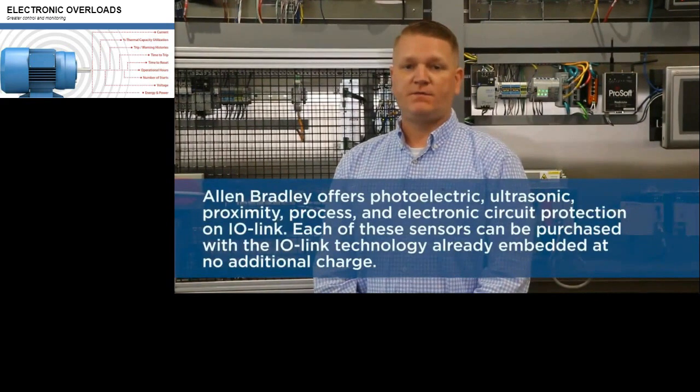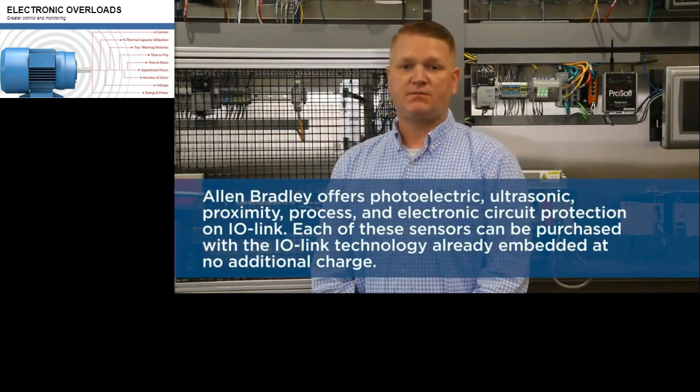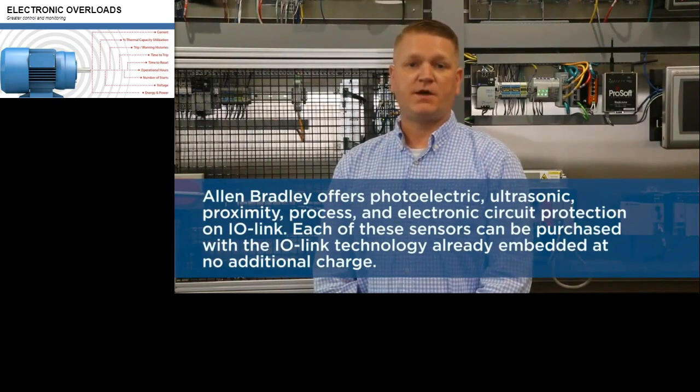Once adding the master into your IO tree in your Logix application, you can get an add-on profile that allows you to enter the IO-Link sensors into the application. Allen Bradley does offer photoelectric, ultrasonic, proximity, process, and even electronic circuit protection on IO-Link. Each of these sensors can be purchased with the IO-Link technology already embedded in them at no extra charge.